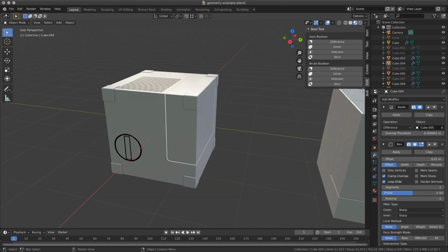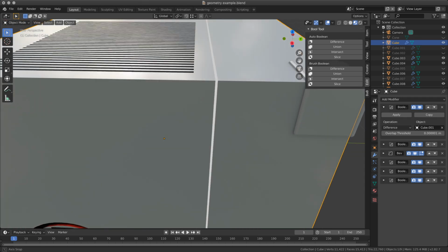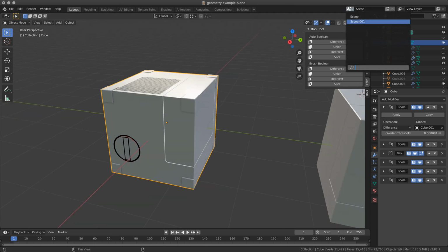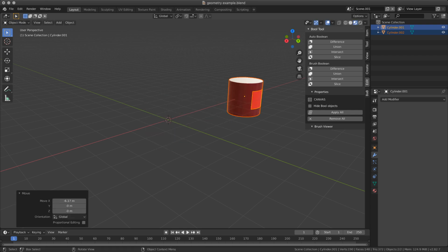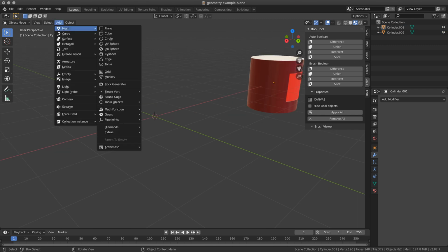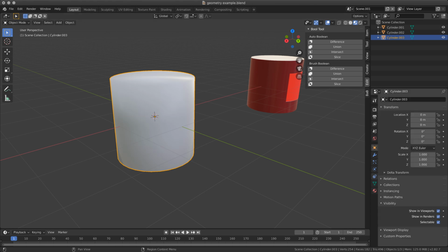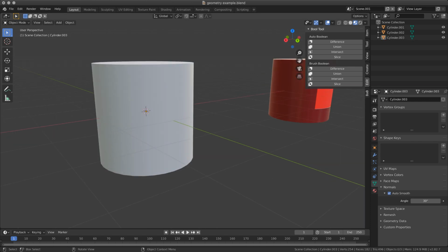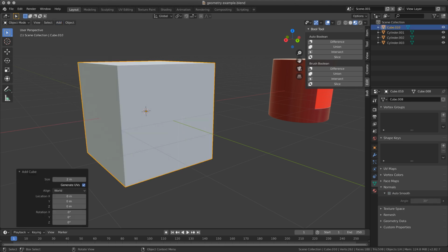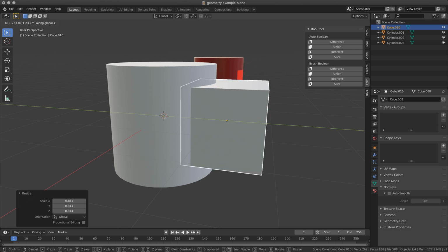In this case, in the first one, I did this in a completely different way. I'll show you how. So let's move our object a little bit away, and let's create a new cylinder, same size, so we're not confused. Smooth, auto smooth, I want the top to be flat. Let's create our cutter, again a cube, again smaller than the cylinder. Let's move it a bit.